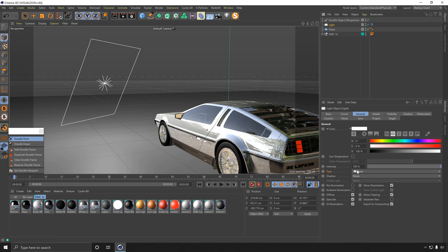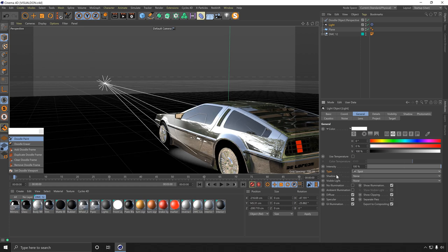And then if we go back to this and change it to, let's say, Omni, the Omni light is sometimes referred to as the point light in different 3D applications, because the light originates from a single point, and then you get light rays going in all directions from that point. Similar to the Omni light, we have a spotlight, except that with this you also get a cone angle, which you can use to direct the light. So it's still point based, and then you have this cone angle which you can adjust.